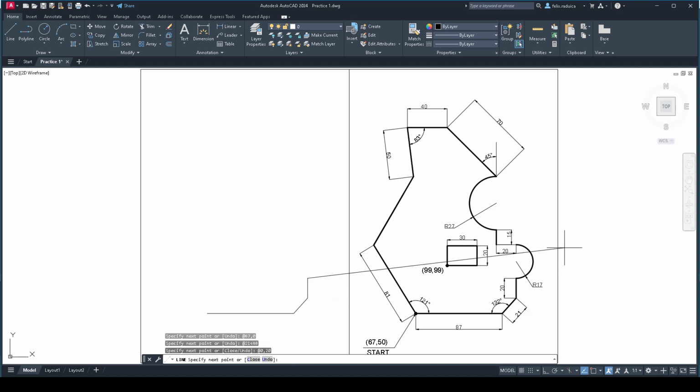Now we have to create this arc, so we tap enter once to finish the command line, and now we need an arc with a radius of 17. So we give the arc command, then the end command to snap to this. Now we have to type C for center and give the center coordinate as at 0, 17, and the end point will be the same, at 0, 17, enter, and the arc is done with a radius of 17.